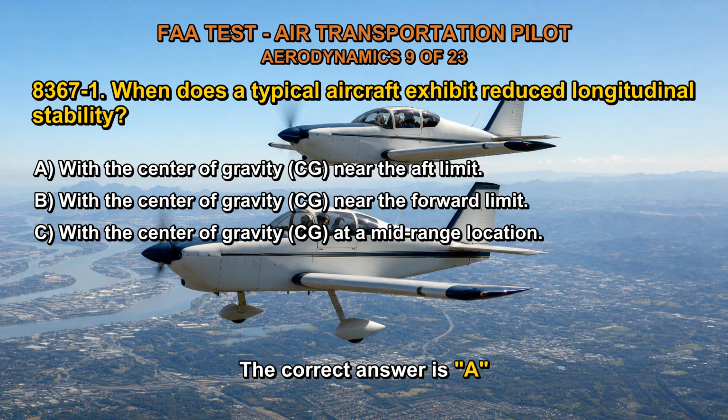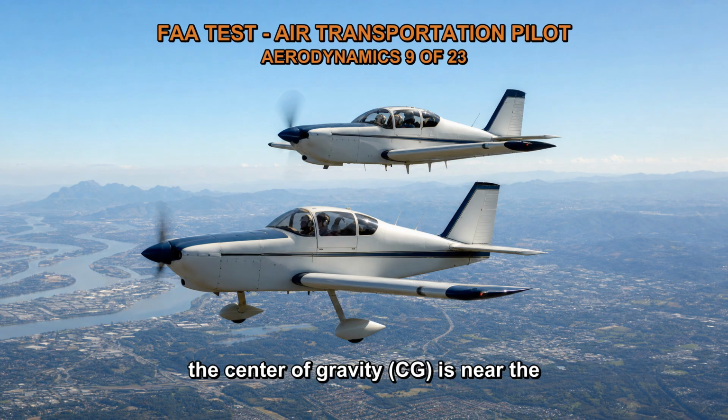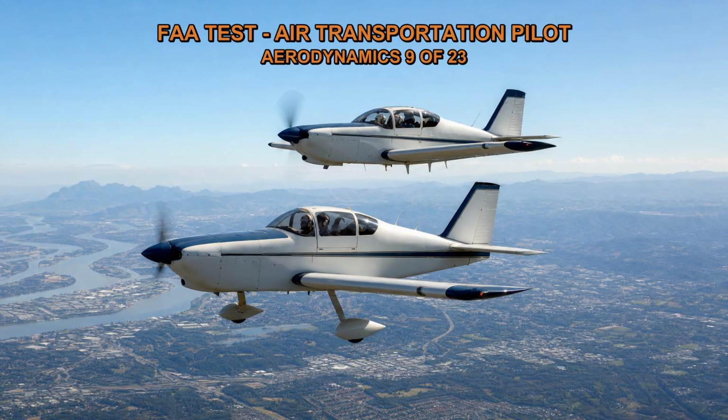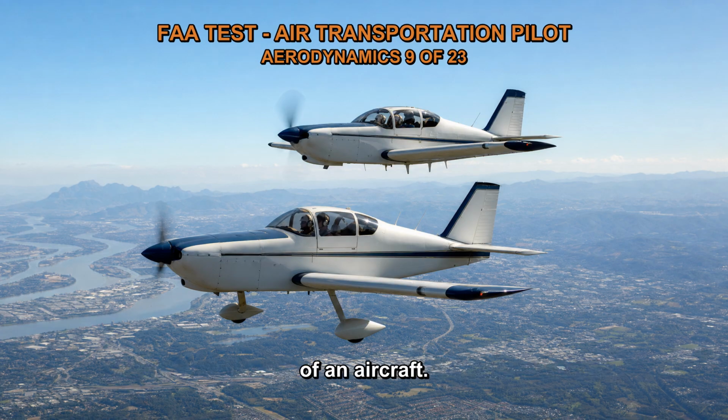The correct answer is A. A typical aircraft exhibits reduced longitudinal stability when the center of gravity, CG, is near the aft limit. Longitudinal stability refers to the aircraft's stability and response characteristics in pitch. The position of the center of gravity plays a crucial role in determining the longitudinal stability of an aircraft.